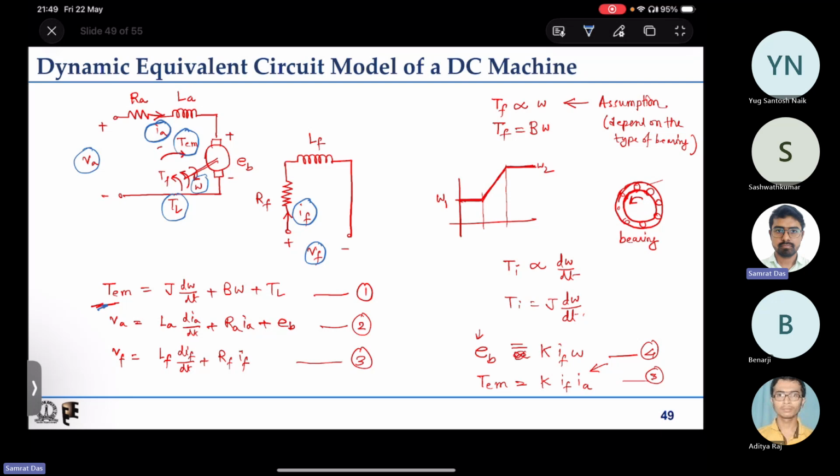So we have some intermediate variables like the currents. If I can bring in flux linkage, that is one too, like the field flux per pole, which is also an intermediate quantity whose information is actually there. The flux is nothing but inductance into current, that is the flux linkage. So we have that information inside this, as the flux is assumed here to be proportional to the field current. So field current is another variable for us.